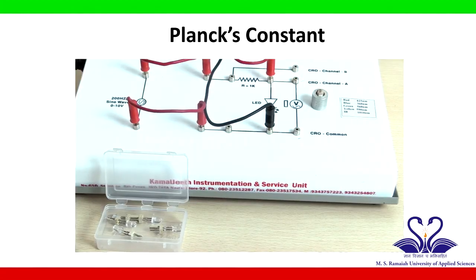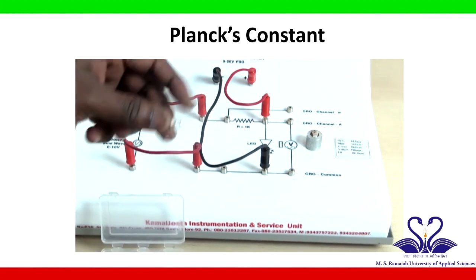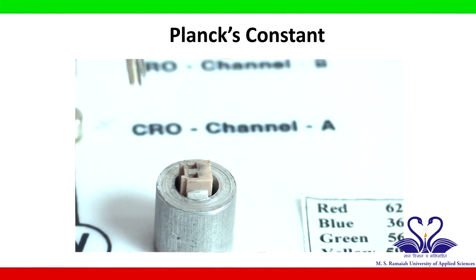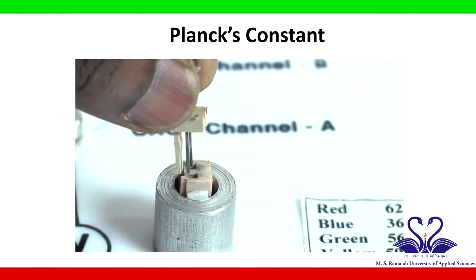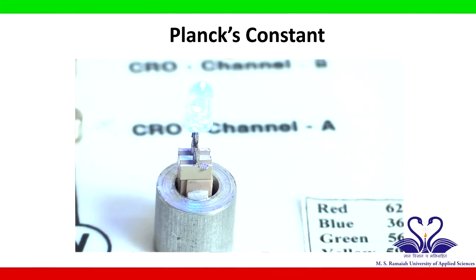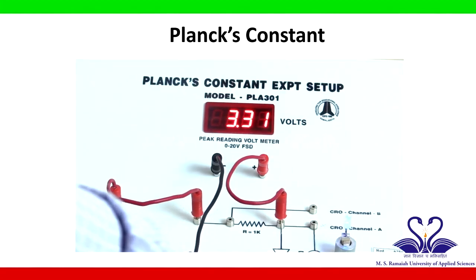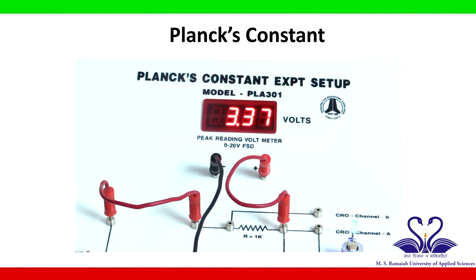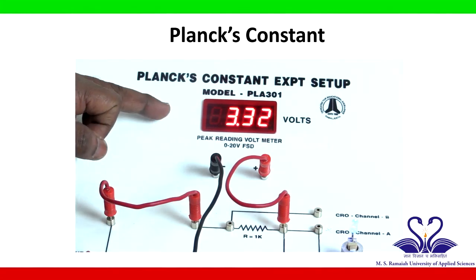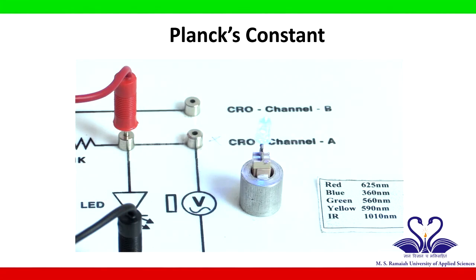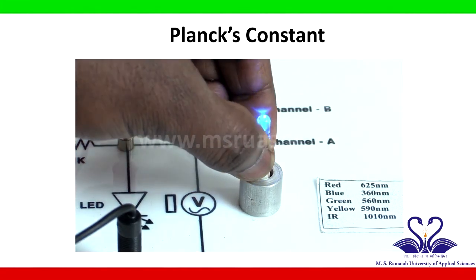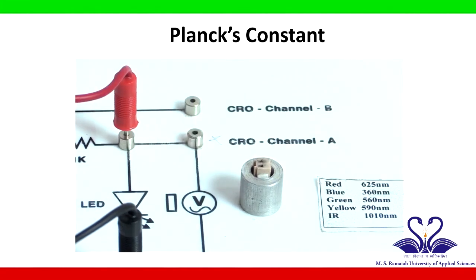Now, take any one of the LEDs and place it in the LED socket. Now, the LED glows blue. Note down the corresponding wavelength from the table given here, and also note down the knee voltage from the voltmeter. Now, remove this LED and replace the next LED.